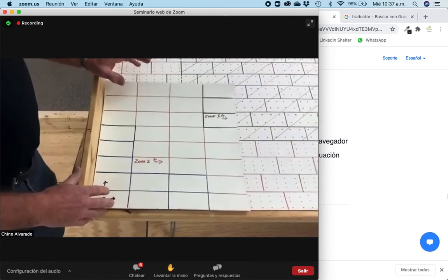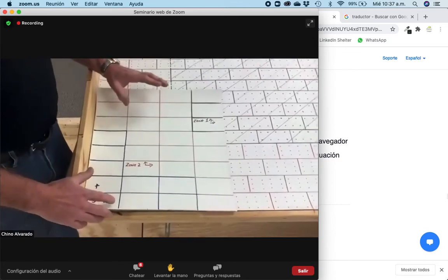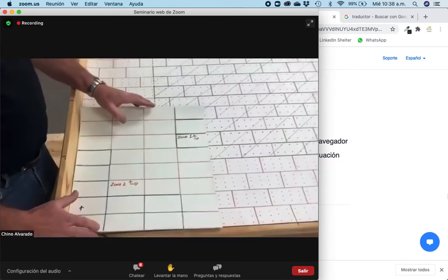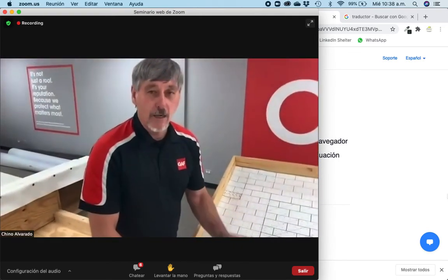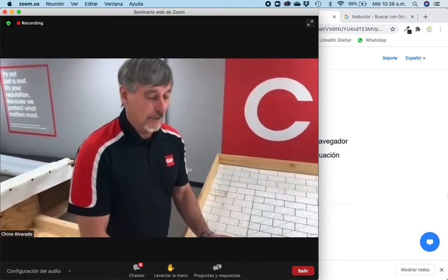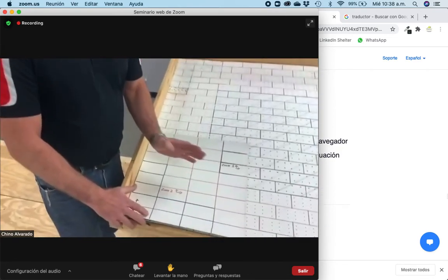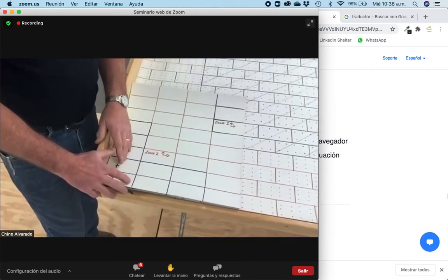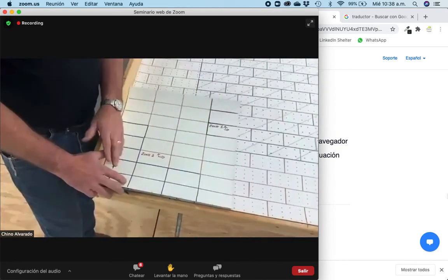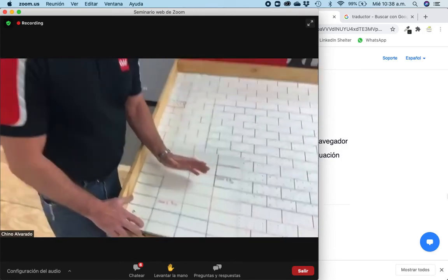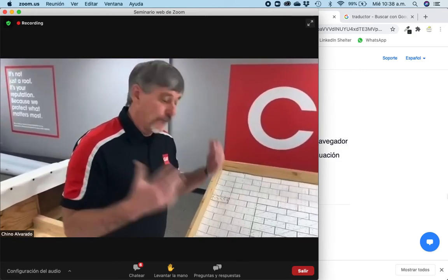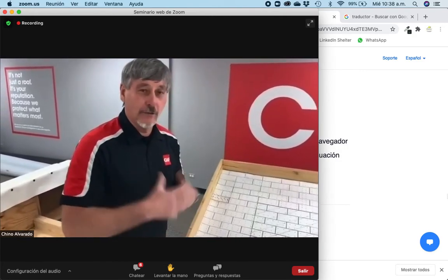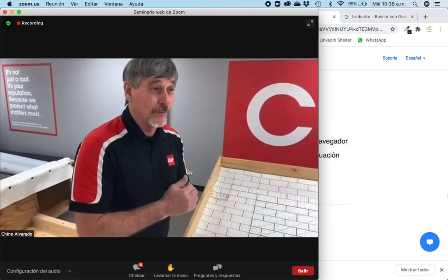Now, I'm going to say something here. I can just hear you guys screaming on the other end of your computers. If you stagger off your bottom layer of your insulation, there is no reason to stagger your top layer. I can hear it now. With GAF. What are you talking about? I get it, guys. I was in the field for a lot of years. It's roofing 101. We've staggered insulation since Christ was a child.